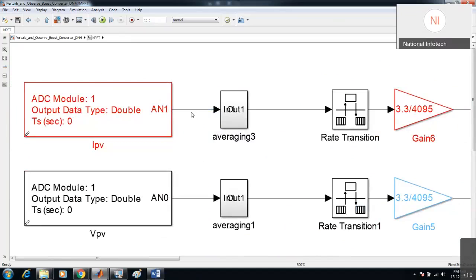You will be getting a count respective to whatever voltage you are providing. You have already seen that video where Rajan sir was varying the ADC port, and we were observing the count on the LCD screen as well as the voltage.